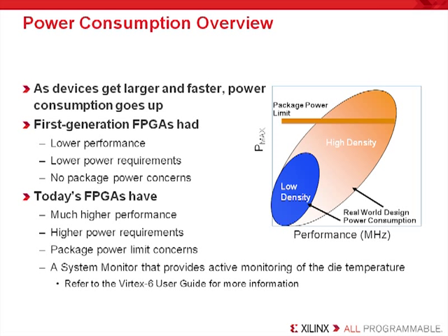To get optimum speed, device utilization, and minimal power, customers need to plan on targeting as much of the FPGA's dedicated hardware resources as possible. This means that users not only have to plan on instantiating the proper resources, but sometimes have to look for creative ways in which to use the dedicated resources. For example, most customers would think to build a FIFO with a block RAM, but most would not consider building a finite state machine with block RAM.